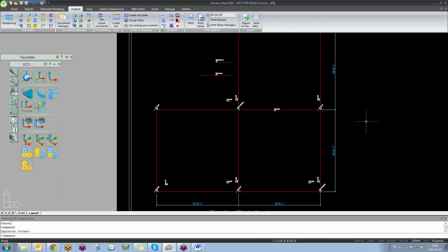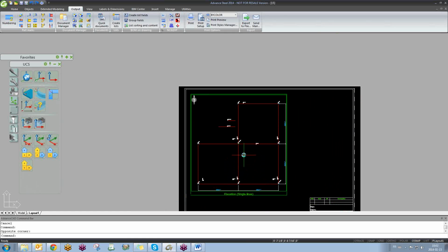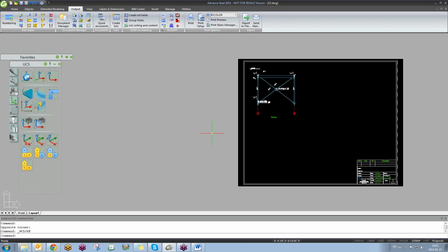Offsets? Yeah. Or if your beams are down like 4 inches below the top of steel of some of the, like say your main steel is at an elevation of 10 feet, but then you got certain portions of your steel that's down 4 inches, will it show what the level offset is on the plan? Mm, you have to put it manually.